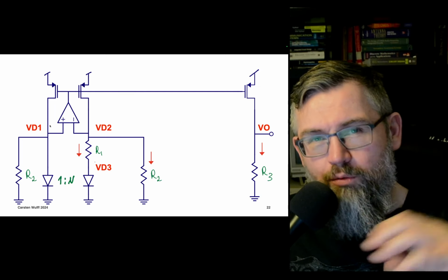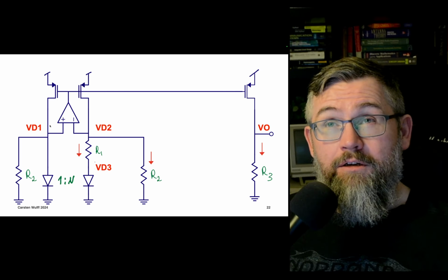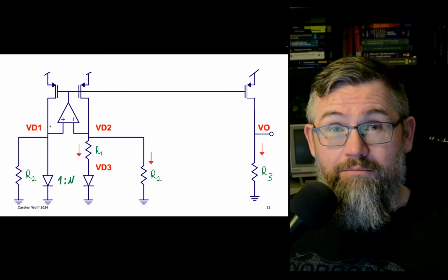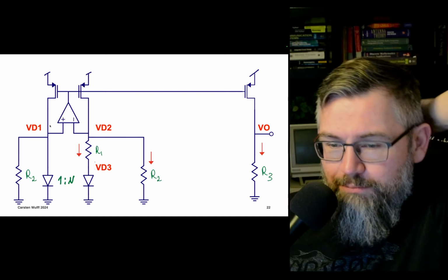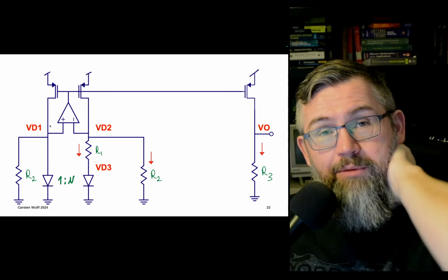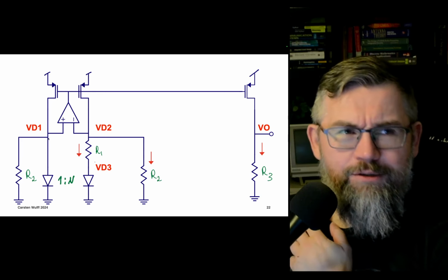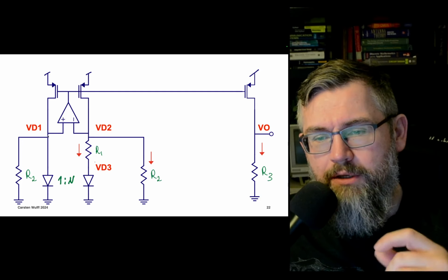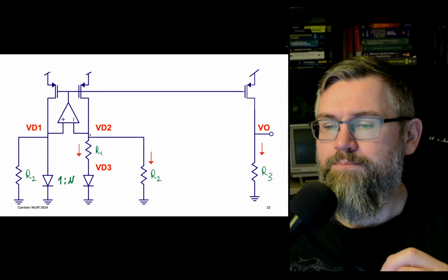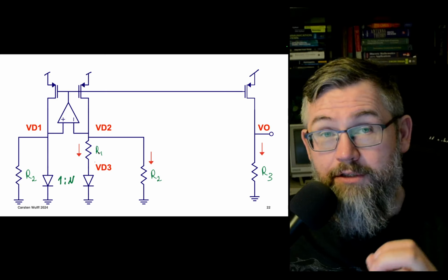So we've now lowered it by at least 300 millivolts, maybe even more. I think with these types of low voltage bandgaps, we can get them down to maybe a volt, maybe even lower, but then it depends on how high the diode voltage goes at low temperature, right? Because at some point that might be a problem. I should also mention that resistors have a temperature coefficient.